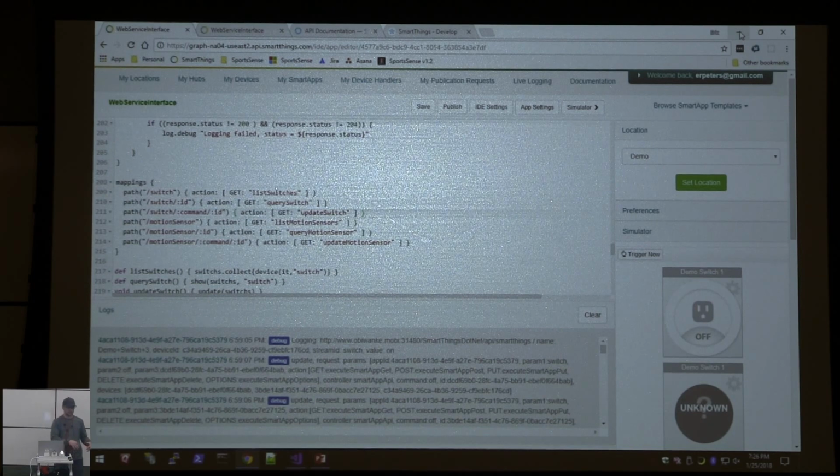The sump pumps have a main float, and then they have an overflow, and those go to a control box. The control box has a normally open, normally closed connector on there, and I ran a hard wire from the security system box to that, and now when they trigger, it will give me a security alert. You can program the security system to handle that in a variety of different ways, and in mine, it just dings like it does when there's motion.